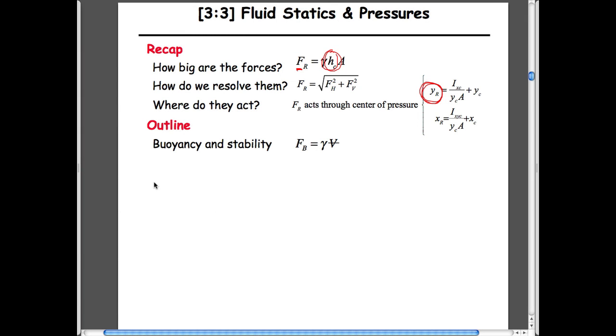So one way to look at that, I think, is to just understand that if we draw pressure in this particular way, and we look at the depth, which we'll call positive y, in everything we've done. Y, of course, can be inclined, which is the same as our negative z. Remember that. We haven't used this here, but that's the convention we've used. And if we look at the slope of this curve, it is equal to y times the unit weight of the fluid, which has been water.